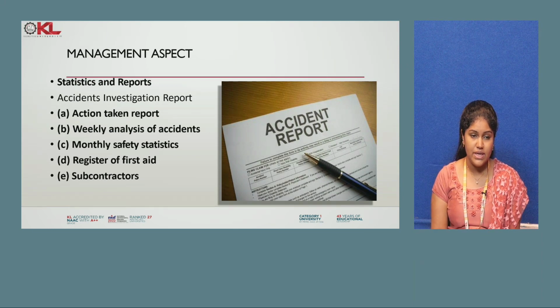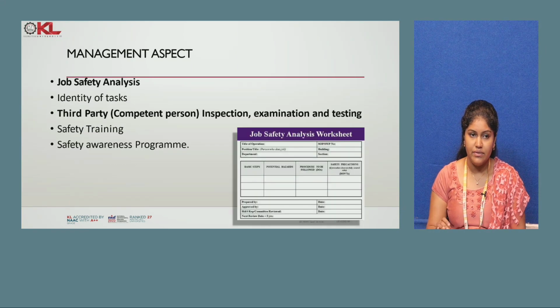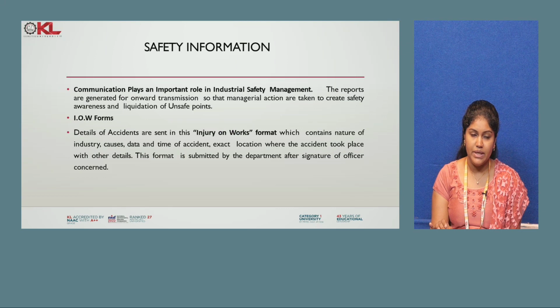Continuing with management aspects, there should be proper statistics and reports, that is the accident investigation report. It will give the action taken report, weekly analysis of accidents, monthly safety statistics, register of first aid, and subcontractors will be given. Then job safety analysis, identity of task, third party inspection will be done, and safety training and safety awareness programs will be given.